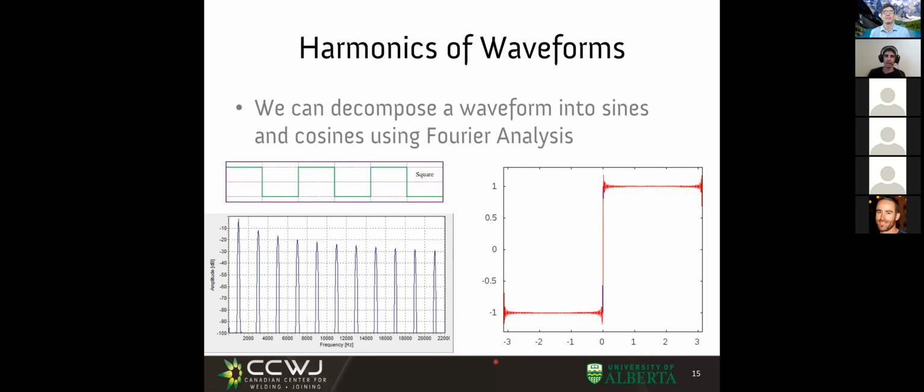Other pulses are related with the droplet. If you see the droplet has some oscillations, and that means it has a natural frequency of oscillation. So with different pulses, you can have different forms of heat input, but also different ways of exciting the resonant frequency.